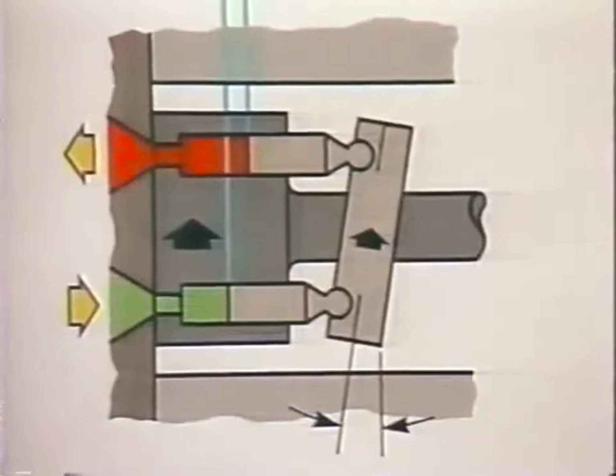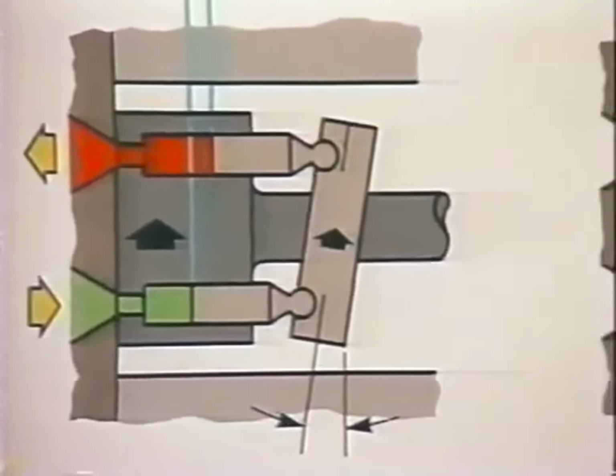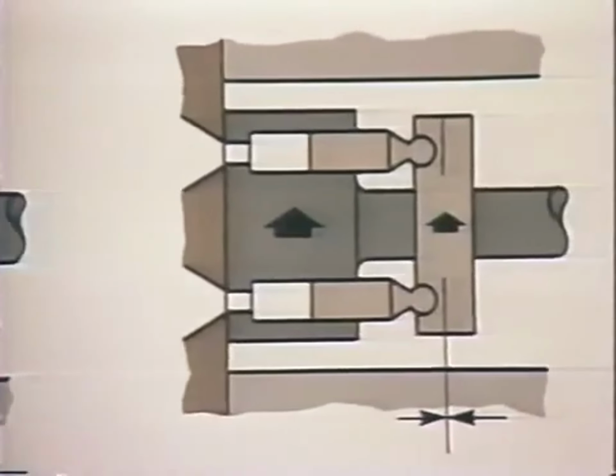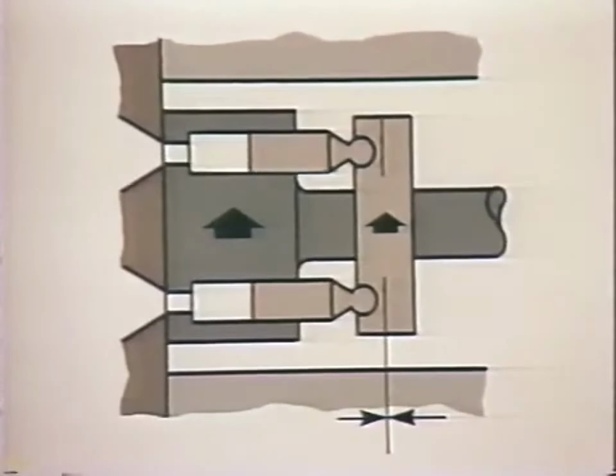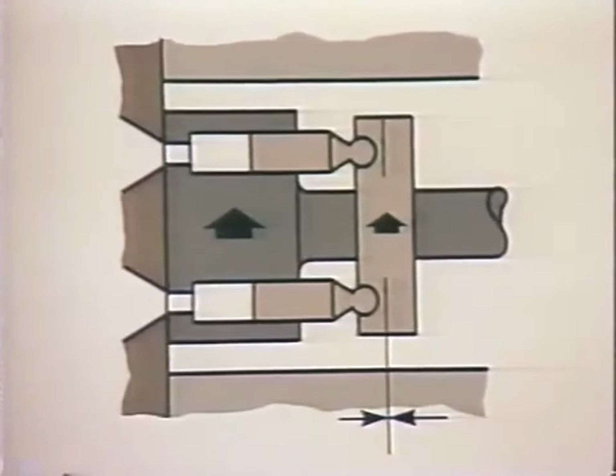The piston stroke is reduced as the swash plate is moved towards center. At the center position, the swash plate is at right angles to the drive shaft, and there's no movement of the pistons in or out, and no flow into or out of the pump. Crossing the center with the swash plate would again start the pistons moving, but in the opposite direction, and flow from the pump would be reversed.